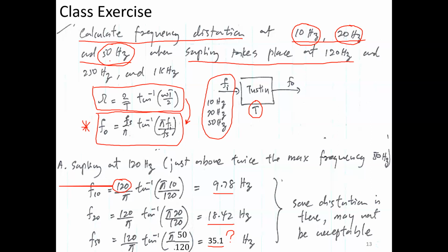So this is the reality of dealing with signals in discrete time. So that is why it says Nyquist theorem is not the rule to be followed, right? It is the ultimatum. So therefore, half of the Nyquist doesn't mean anything in reality, right? So if you are a control system designer and you have the proof here, 50 hertz has a lot of problems. 20, I think 20 is okay. 20 hertz is seen as 18 hertz, close enough.